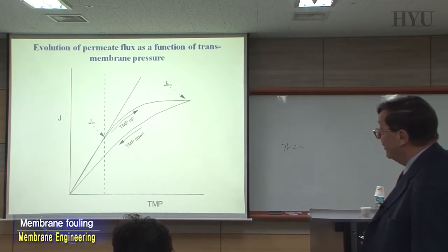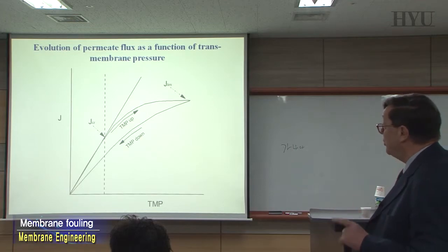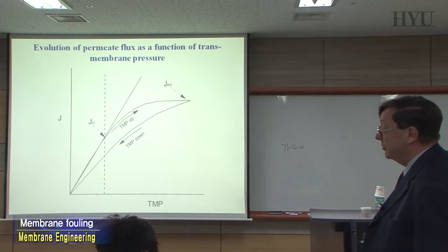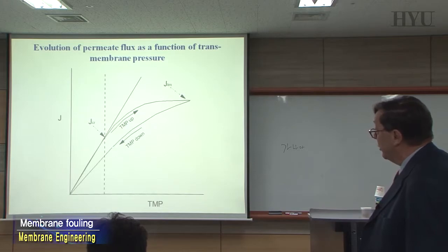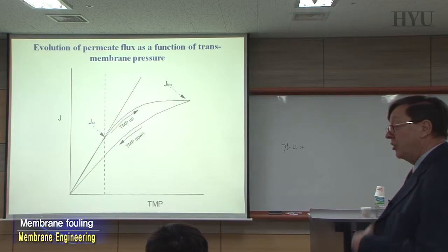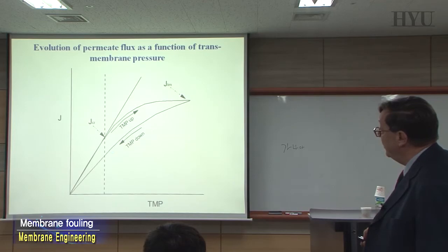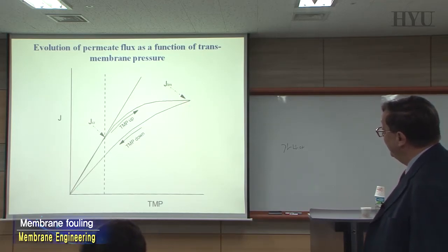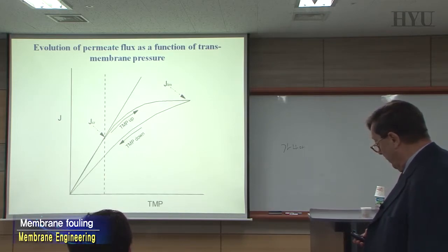After this critical flux, you start to have this kind of behavior related to the fouling, which is not reversible anymore. If you stop here, when you go back, you have a hysteresis. So you have a deviation, and you cannot restore the initial flux. That's the situation we want to avoid, because it can create more and more problems, and the irreversibility is becoming worse and worse. If you go up again, you have this one going down here and down here, so you really foul the system. That is what we have to avoid.